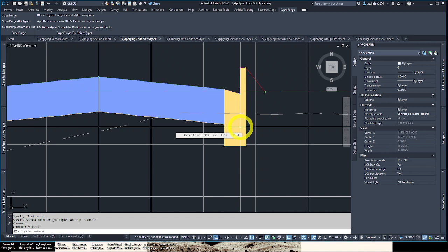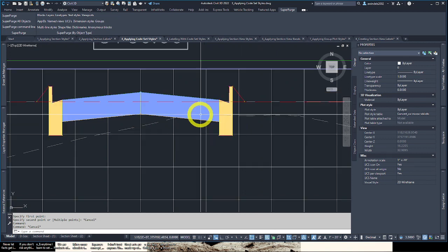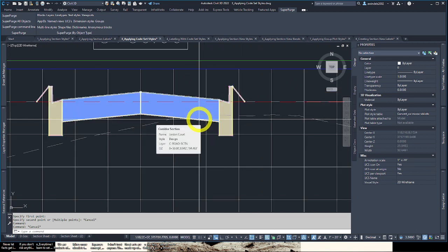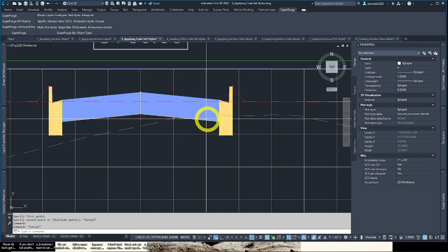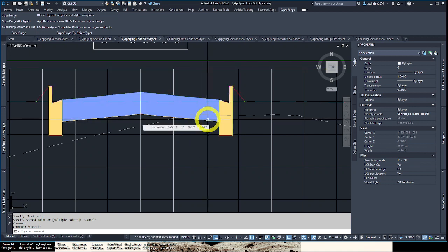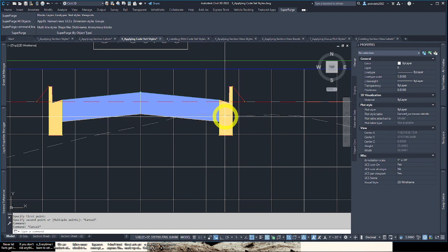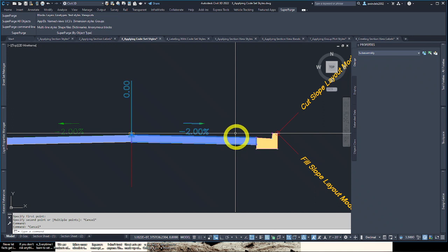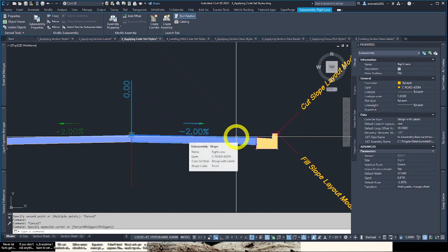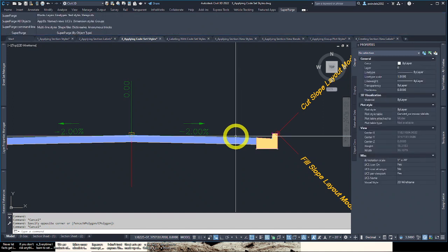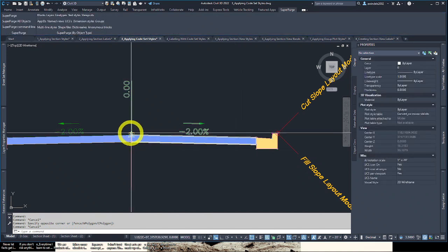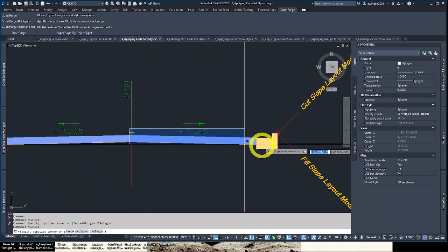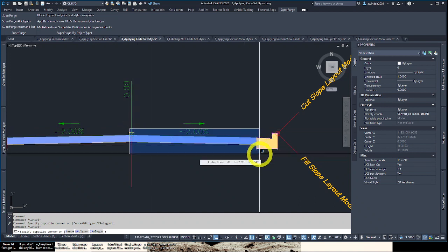So best example is one code that is used quite often is pave. So this basic lane transition assembly, for example, in your corridor uses a rectangular shape to represent the lane, and the pave code inside of it is assigned to this shape as a property of the subassembly. So it's shown as pavement, and when we do quantities later, this is a pavement. It has a pavement code inside of it, inside of the shape. Shapes have styles, just like all other Civil 3D objects. So the points, links make shapes, and these shapes have their own styles too and their own appearances.